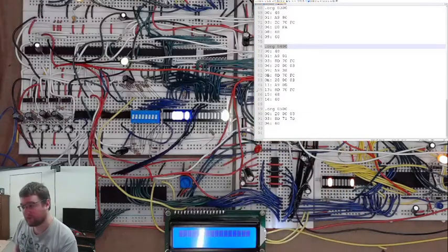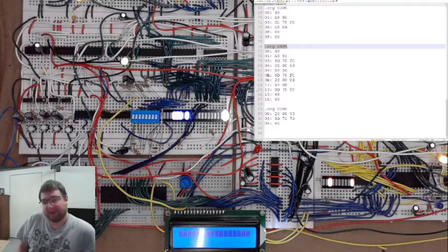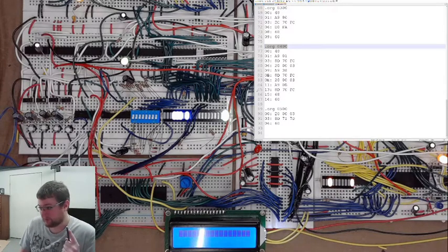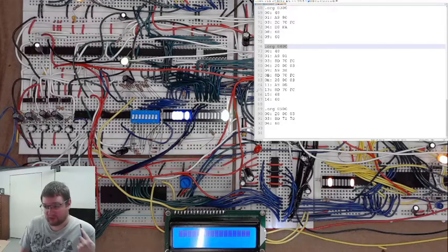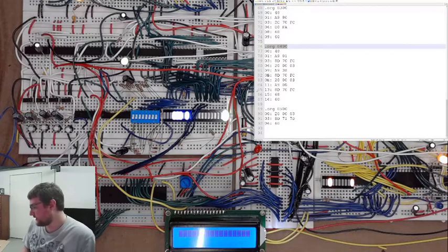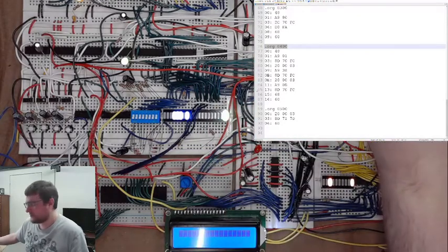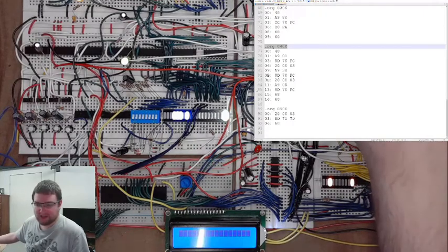the SPI up to 20 megahertz, which will greatly increase that speed. And the cool thing is, because most devices run at 20 megahertz SPI, at least. Some of them even do 40. If you can ever run 40, you're like in the gold. Which on a PCB we probably can, but not everything can use 40, so you can't rely on that. Whereas if you rely on doing everything at 20, then it takes like 8 clock cycles of the CPU and